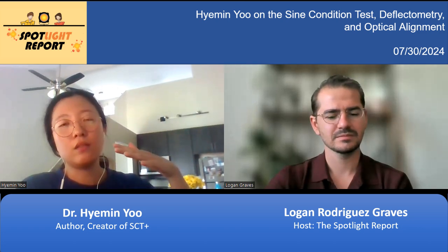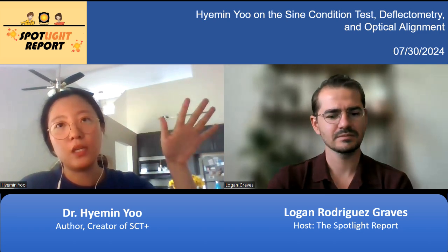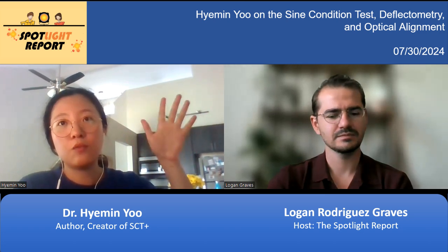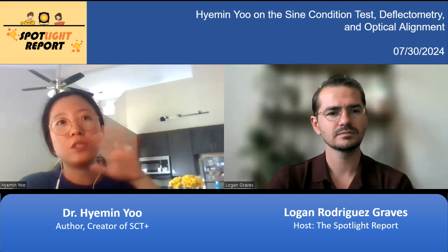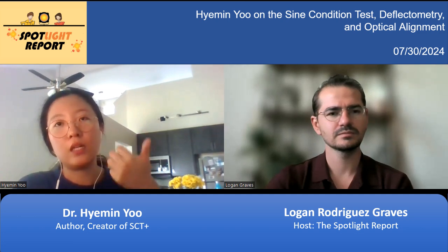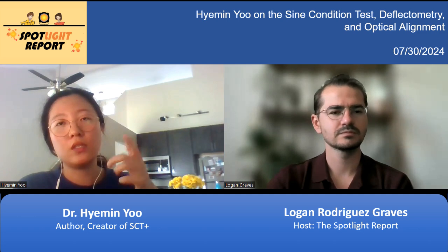So that's the flow. Abbe started the Sine condition for designing optics with good image quality over the field of view, but it can be applied to the misalignment problem because the major aberrations from misalignment are linear astigmatism and linear focus.